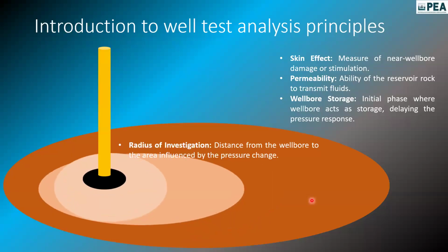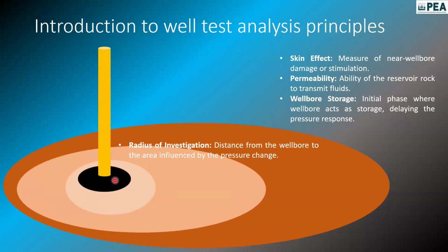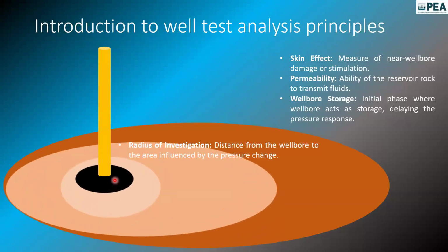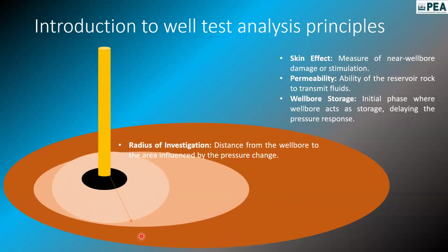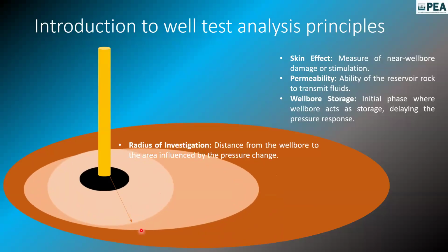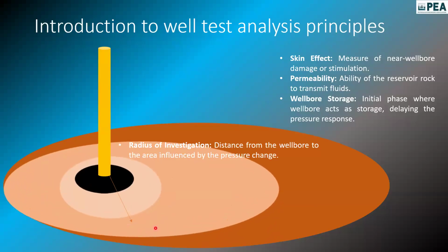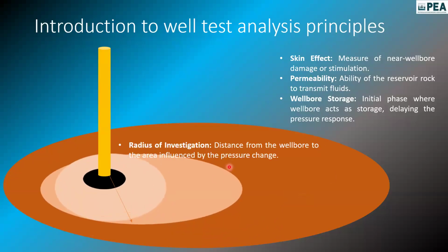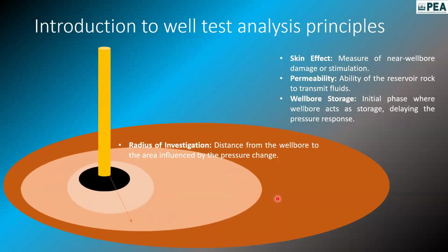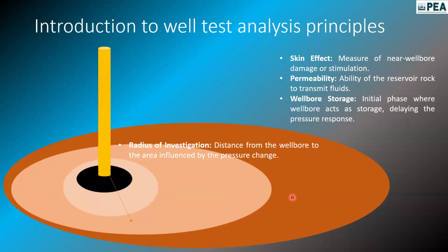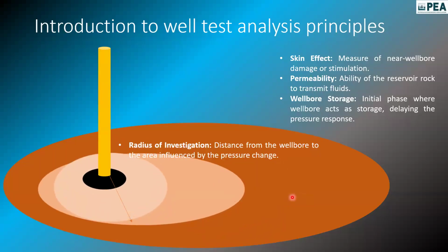Here the pressure will be maximum near the boundary, and near your wellbore the pressure will be minimum. Imagine at a particular time period, if you want to measure the pressure radius of investigation, you can see how much extent it has been moving forward into the wellbore. Based on that, you can estimate the radius of investigation. But if you have to estimate reservoir pressure in this drainage boundary, different colors will indicate different pressure. Moreover, the one close to the boundary will have the highest pressure, and the one close to your wellbore will have the lowest pressure.